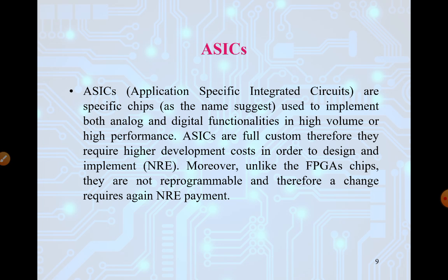So the contender of ASIC is FPGA, field programmable gate arrays. But the problem with ASIC is they are not reprogrammable. They are fixed and the budget is very high, because for designing ASIC we need fabrication. After the custom design of all the parts, we send our simulated design as a tape out. We have to send the tape out to a fabrication industry, in China or some other fab. Then we get our design fabricated, maybe 1,000 pieces, 2,000, 10,000 pieces based on our product demand. And then you have to test it, so the cost is much higher, at least 5 lakh Indian rupees. So the cost of ASIC is much higher.